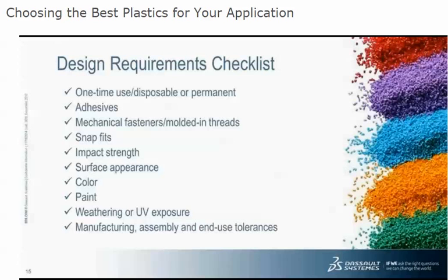Will it require snap fits? When we talk about plastics, some materials are appropriate for snap fits, some materials are not, because some materials might be too stiff and brittle, so that when you try to do a snap fit, the snap fit just breaks off. And again, the list goes on and on and on. Another set of the list here.